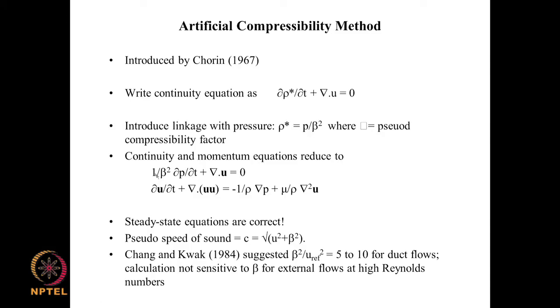Okay. So we can solve this for P here or solve this for rho, use this to get P and substitute that P in this, and here we have an equation for u, x momentum equation or y momentum equation, in which pressure is no longer an unknown, it is already deduced from your continuity equation. Okay.